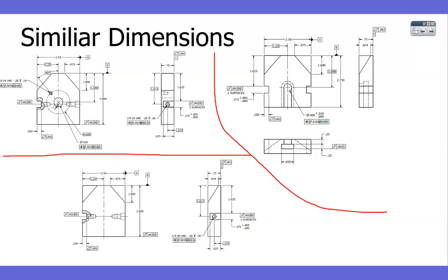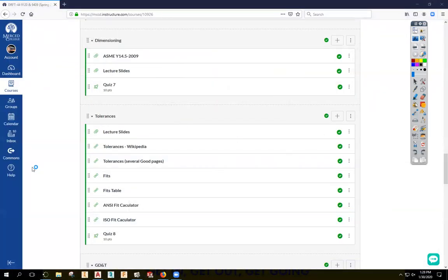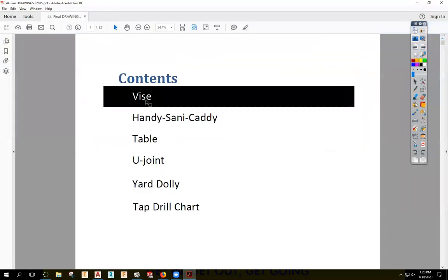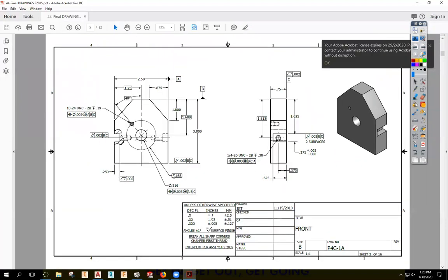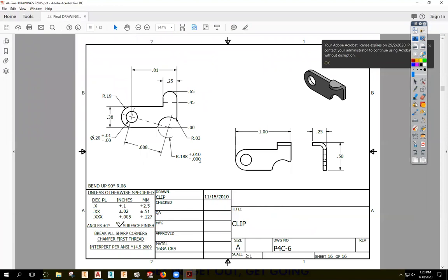But if we look at this part, this hole right here is on a radius dimension. And if I look at the part that goes right there on top of it, that goes through that hole, and it goes over here, that little clip, it's got that same radius called out. Or it's a chain dimension, but it's that same number. So here's that. The radius of that circle is 0.688. If I go and look at this piece, 0.688. It's not a measurement that's going straight across or up or down. It's going from that center point to that center point.